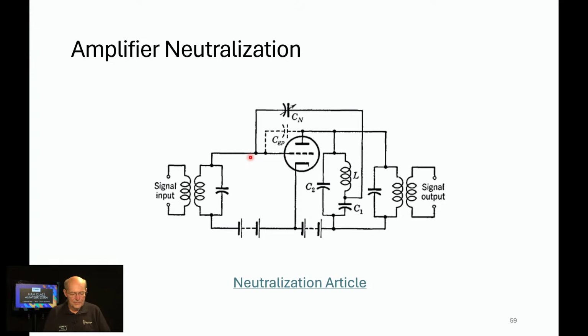which neutralizes the amplifier. Now, if you have a tube amplifier or ever buy one, they're available at pretty good prices on the ham market. Normally, in the documentation for the amplifier, there will be a neutralization procedure that you can use if you ever change the tube. Because the tubes are slightly different, even though they might have the same part number, the internal capacitance varies somewhat between one tube and another.